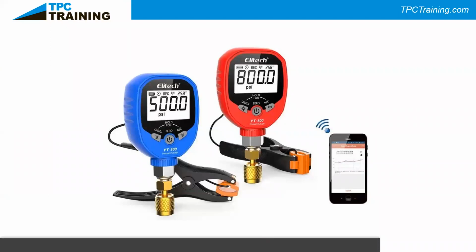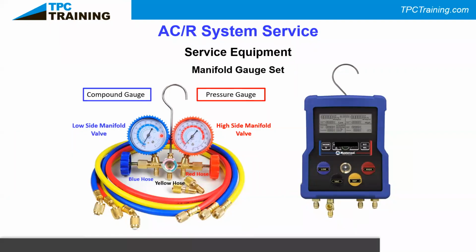Now, analog gauges look like this right here. We have a needle that's going to go across and show us a pressure on our gauge. And these pressures on our gauges are showing us what the system pressure is, above atmospheric pressure and below atmospheric pressure on the blue gauge, and on the red gauge, just reading pressure above atmospheric. Why is a blue gauge called a compound gauge? Because it can read above and below atmospheric pressure. The red gauge is meant for just above atmospheric pressure.